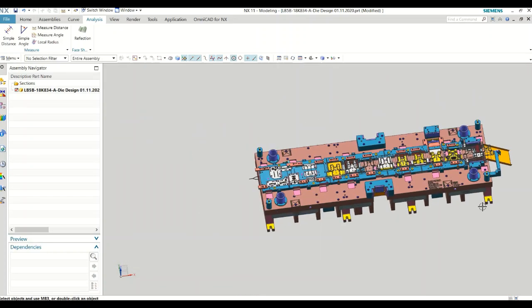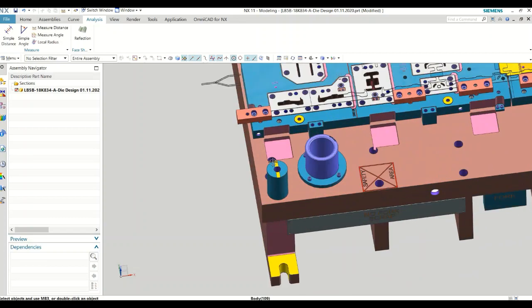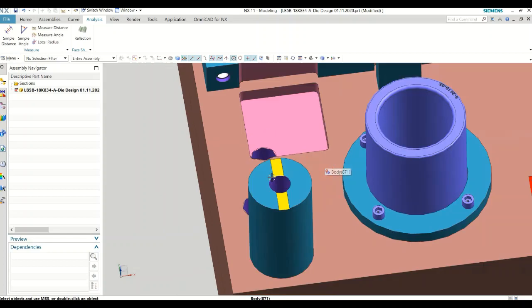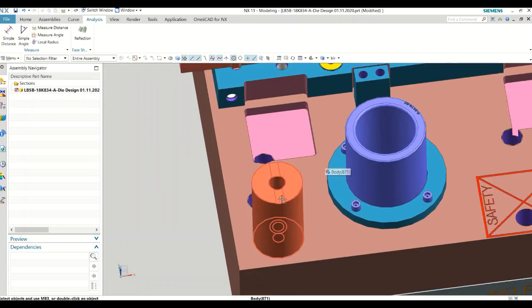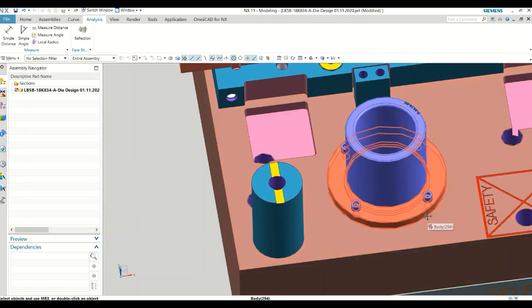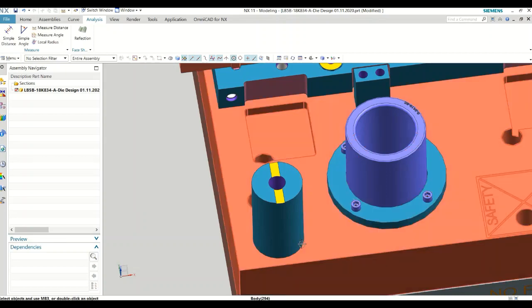We keep a very soft aluminum wire here. When the upper die comes, whatever elements are there hit against it, and it gets thinner and thinner. We keep checking using a micrometer or a vernier caliper, and as soon as it reaches 1.27 we know it's done.